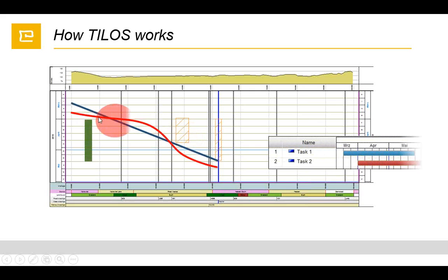Also, some of the activities can have different productivity rates at different areas. In Primavera, we manage by splitting and dividing our tasks into different WBS. We link them as many activities, representing maybe some distance for each 100 meters or each 500 meters based on our project. In Tilos, we can represent just one activity. It will look at your calendar, your productivity rates on the site, and the predecessor and successor links in the project.